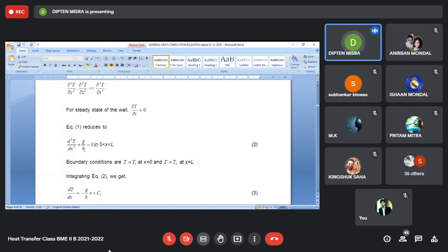Same thickness, same boundary conditions T1 and T2, same conductivity, same G dot, even if their thermal diffusivity varies, for this class of problem the solution will be the same, because the problem specification does not require specifying alpha. It is independent of alpha.